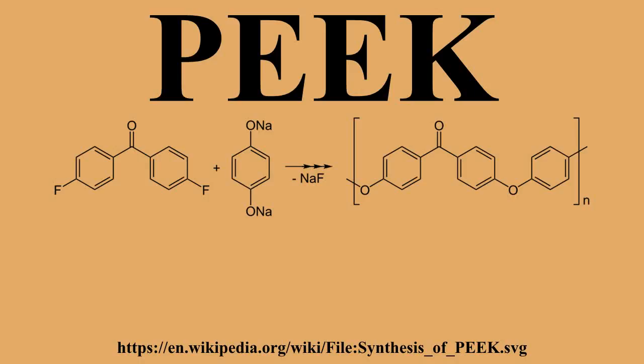It is highly resistant to thermal degradation as well as attack by both organic and aqueous environments. It is attacked by halogens and strong Bronsted and Lewis acids as well as some halogenated compounds and aliphatic hydrocarbons at high temperatures. It is soluble in concentrated sulfuric acid at room temperature, although dissolution can take a very long time unless the polymer is in a high surface area to volume form, such as a fine powder or thin film. It has high resistance to biodegradation.